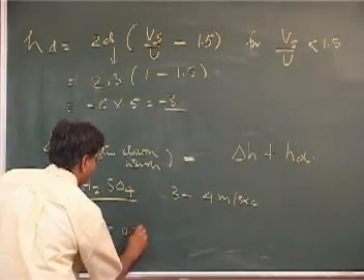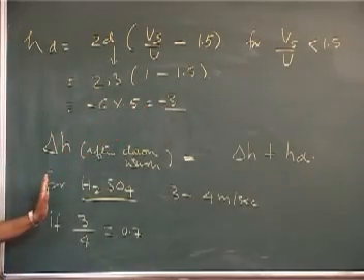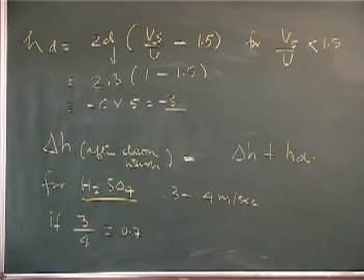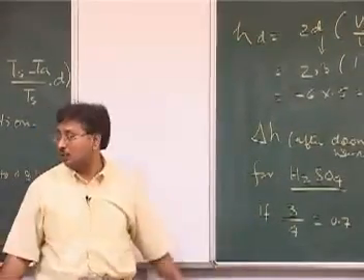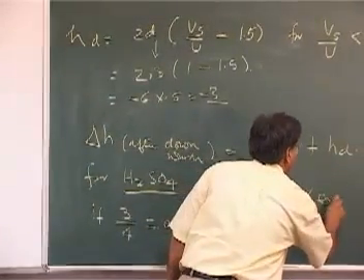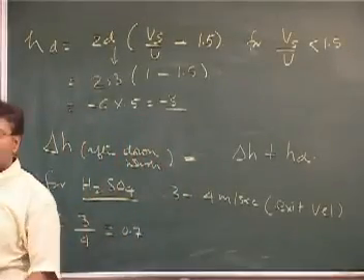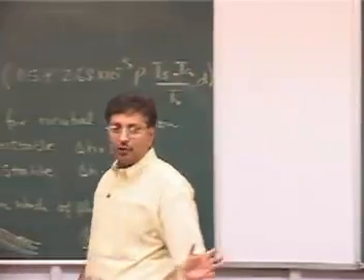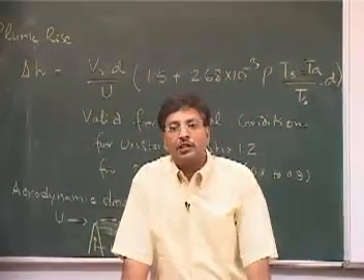So the ratio comes out to be nearly 0.7, much less than 1.5, and the sulfuric acid plant, which is responsible for SO2 emission and acid mist, will have its plume brought down, and the people surrounding that area will suffer a lot, because the plant was designed for a low stack exit velocity of 3 to 4 meters per second. A chemical engineer may not know all these things, but it all becomes interdisciplinary when you are doing calculations for a sulfuric acid plant.